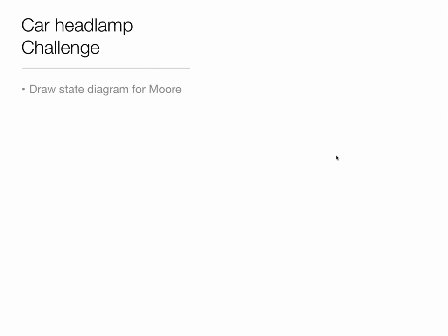And these are the things you'll need to do. You need to draw yourself a state diagram. For now, start with the Moore machine. Write down the state transition table. And looking at last week's lectures, try and reduce the states as far as you can go. When I did it, using an exhaustive approach, I ended up with 5 states, and I managed to reduce that down. I can't remember whether it was to 4. I think it was down to 4.